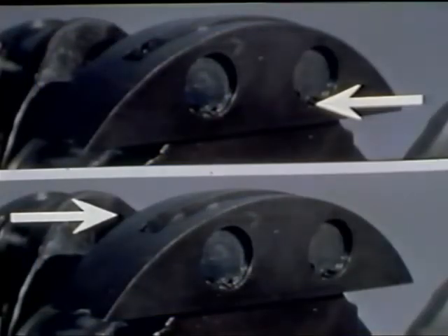At this point, let's take a look at the resonant frequency of the engine as it operates. Here, vibrations of both the engine and propeller at certain engine speeds will cause damaging vibrations. To prevent this, counterweights are usually installed on loose-fitting pivots and allowed to freely rock back and forth as the crankshaft spins. The oscillating action of these counterweights changes the resonant frequency of the rotating mass, so that it will not be excited by the firing impulses in the normal operating range.